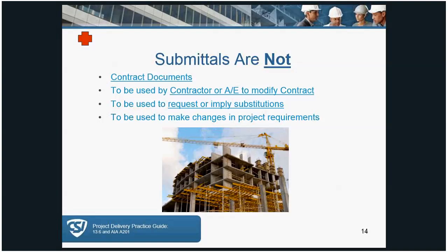This is extremely important to remember: submittals are not contract documents. So this really should have a double plus sign on it. And if you go back to the A201 document, you'll see very clearly in there that it's specified that shop drawings are not contract documents.